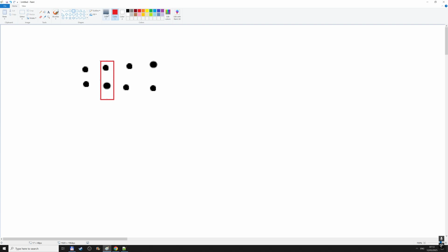Now, I could do an LDMIA and read 4 words at once and read all these pixels. But then I have to unroll the code so that I keep them in registers. And as I move to the right, I have to write some more sophisticated code.